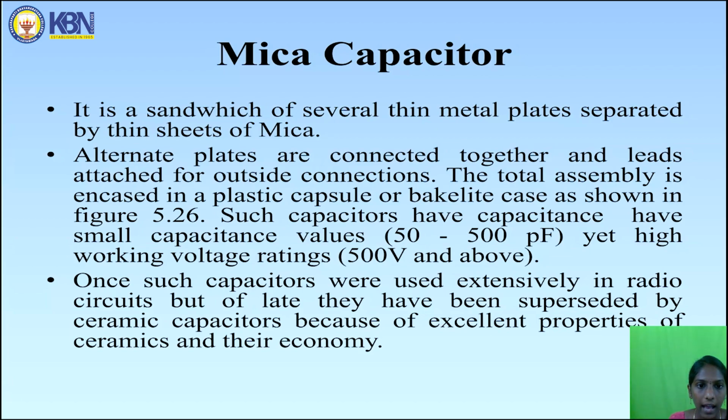It is a sandwich of several thin metal plates separated by thin sheets of mica. Alternate plates are connected together and a lead attached for outside connections. The total assembly is encased in a plastic capsule or bakelite case.